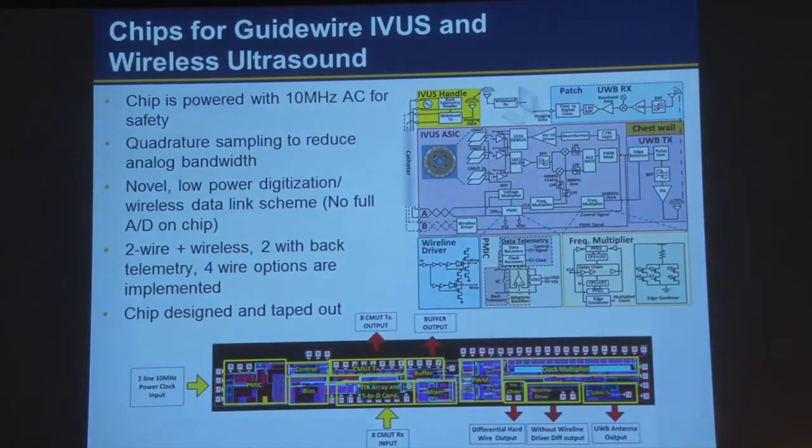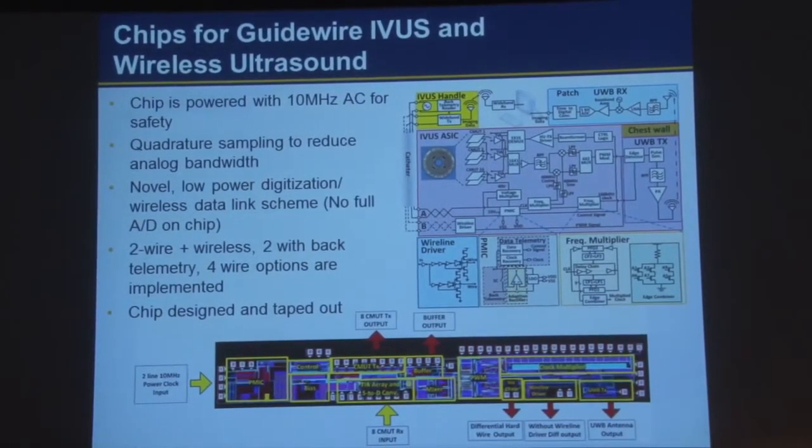Now the electronics. That's actually the harder part for this project. But we actually have 3 options. So if you look at here, we have our device. We use the 2 wires for AC power, okay? And this is AC power for better safety, so that you don't have the DC along the line. You generate your DC power here, and then you multiplex your input channels.